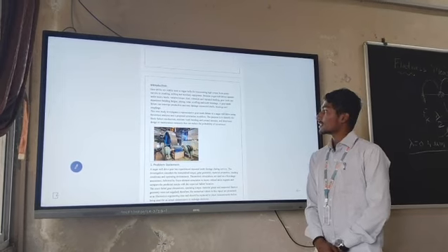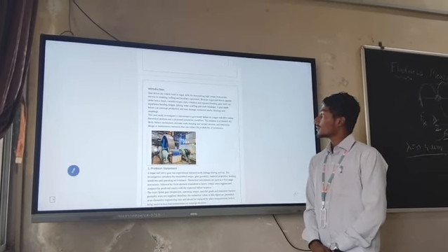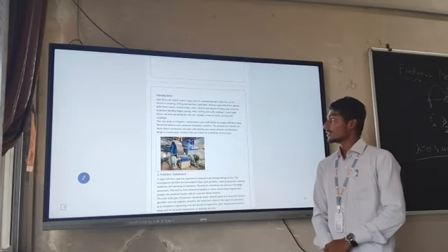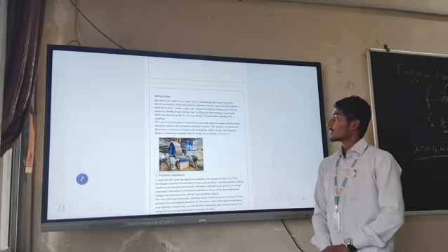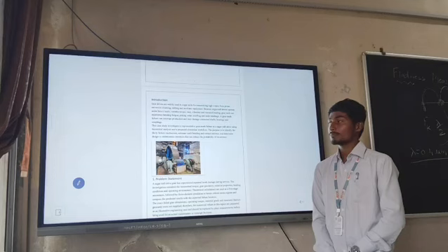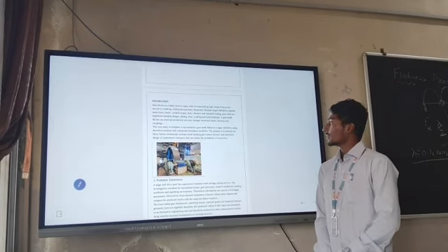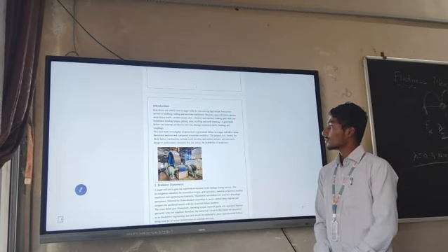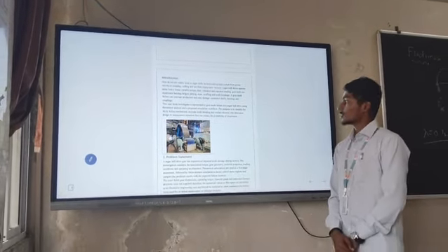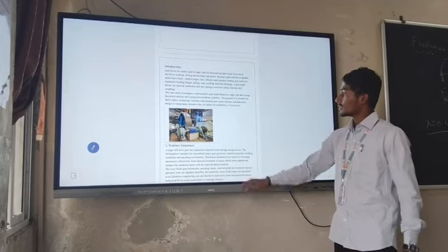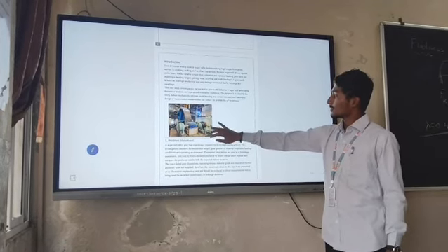This case study investigates representative gear tooth failures in sugar mill drives using theoretical analysis and proposes a simulation workflow. The purpose is to identify the likely failure mechanism, estimate tooth bending and contact stresses, and determine design or maintenance measures that can reduce the probability of recurrence. This is the sugar mill industry gears.